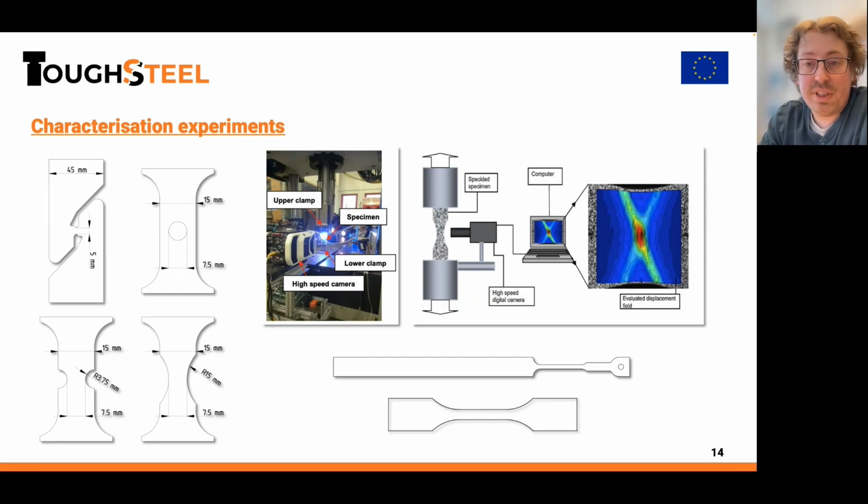Here I show some different tensile tests we usually use when calibrating finite element models. And these are used with a 2D DIC and an internal code to obtain fracture strains and post-necking hardening directly from the experiment, so we don't have to do inverse modeling in finite element. But I believe the next speaker will speak more about this.